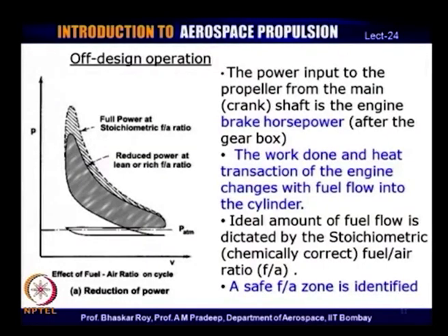During this entire process of operation, the engine has to continuously operate at various operating conditions, and as a result it has to create more power or less power during all these operations. As a result, the power input to the propeller from the main shaft is finally the consideration, and that is referred to as the brake horsepower. That is the power finally supplied to the propeller.